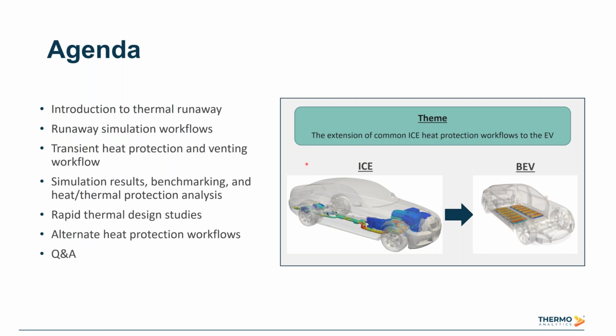So another common theme here for this webinar, especially when we're talking about these alternate workflows, is the extension of common internal combustion engine heat protection workflows to the electric vehicle. So we have a long history here at TAI of performing underhood and underbody analysis for ICE vehicles. And along with that, over the years, we've developed a wide array of heavily validated simulation workflows in heat protection. And the reason there's so many is that these workflows range all over the classic spectrum between accuracy and computational time. So each one is the optimal solution for the specific customer. So the theme here is that it turns out that a lot of these workflows are also applicable to the EV for thermal runaway.